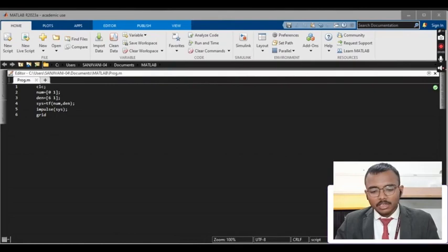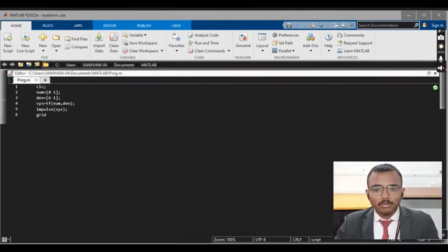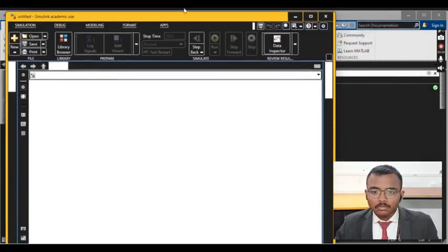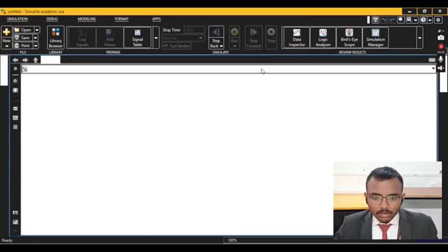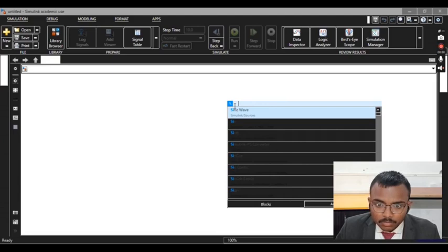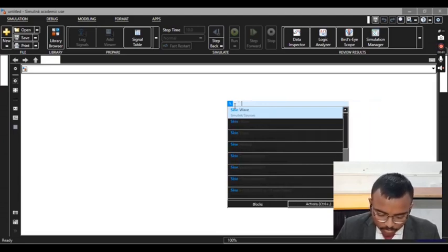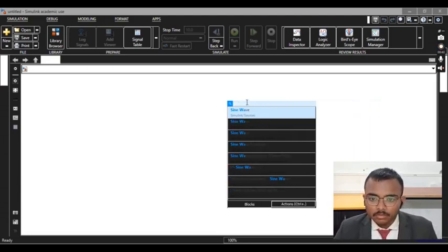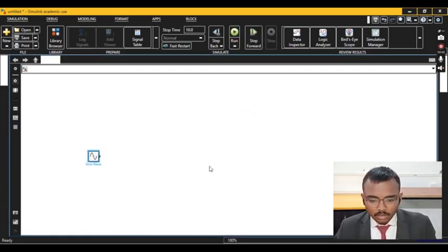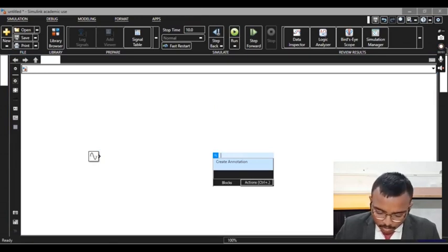As previously, Sanket explained first order for standard signals, step and impulse. Now I am going to explain the sine response. First we go to our simulation and add a new blank model. Now we take components. First was the sine wave. Now rearrange that. Secondly, we take the sum.